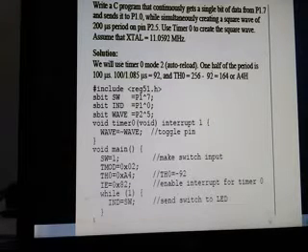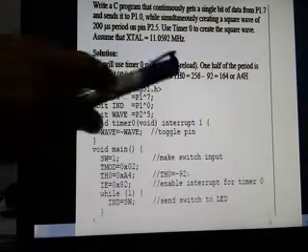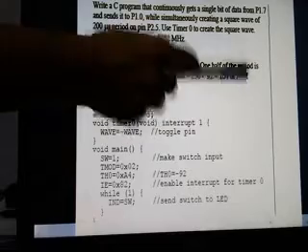So we have to use what? Timer interrupt over here. Which timer interrupt? Timer interrupt 0. Okay, use timer interrupt 0 to create a square wave. Assume the crystal frequency. So we are going to do all the calculations first, like we did in the assembly language program we had done earlier. So timer 0 is used in mode 2. It is mentioned that use mode 2. Okay, so accordingly we calculate the value of the count, which comes as 164 or A4H.